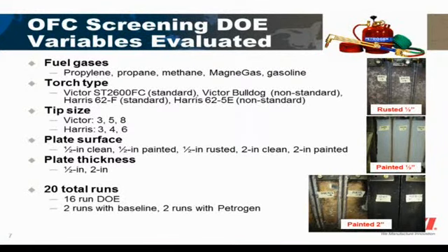The plate surface condition. So our target applications are aircraft carriers. Aircraft carriers generally have half-inch thick material. But the shipyard also threw in 2-inch thick material. You had 2-inch thick clean, which wasn't painted, and then you have what we're calling 2-inch painted. And that's shown here. On the front side, you had vintage paint, and on the back side, you had the residue from where the SHT, the special hull treatment tile, was. So that was on the back side.